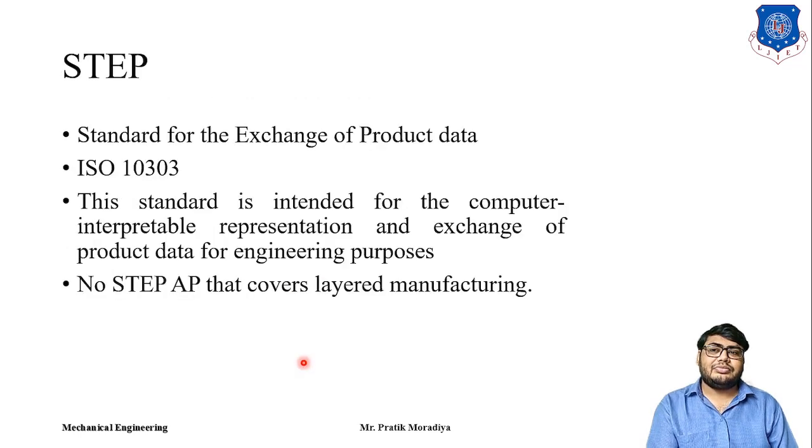Now another file format is the STEP file format. STEP stands for Standard for the Exchange of Product Data. This STEP was developed under ISO 10303. It is an international standard for exchange of product model data, which stores much information about the product model, and it is used for exchange of product data between different engineering applications.